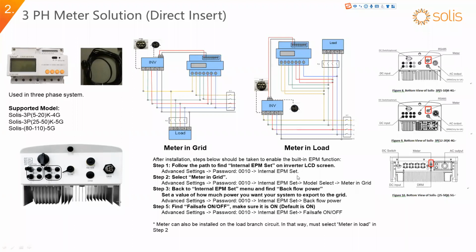But I think the generator will need some very fast control to make sure there's no backfeed current into the generator. So maybe another third-party controller is more recommended than the EPM device.